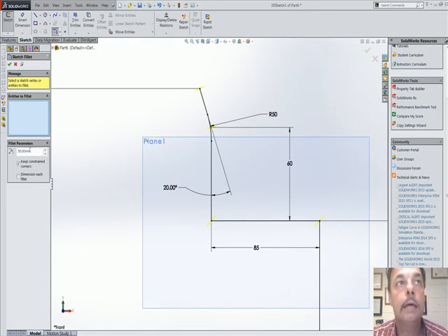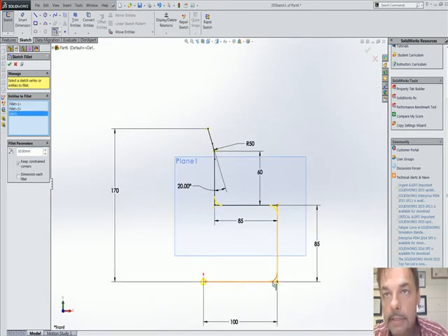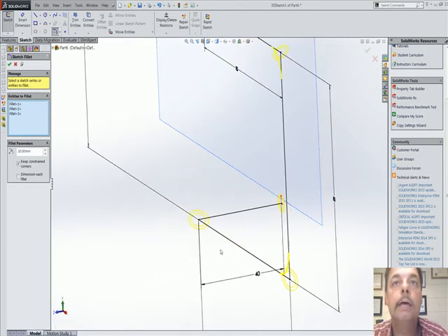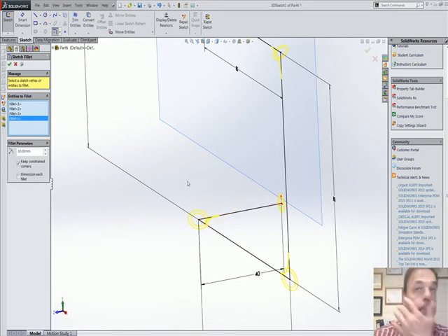Let's go ahead and change this to 10. And let's go ahead and choose this one, this one, this one, this one, this line, and let's turn a little bit and choose this line and this line. I believe that one's a 10 too, isn't it? Yep. Alright, once I got all my radiuses, notice that they're all here in this box. And they're 10 millimeters. And keep constrained corners, so you're going to get a lot of geometric constraints here. Hit my check button.